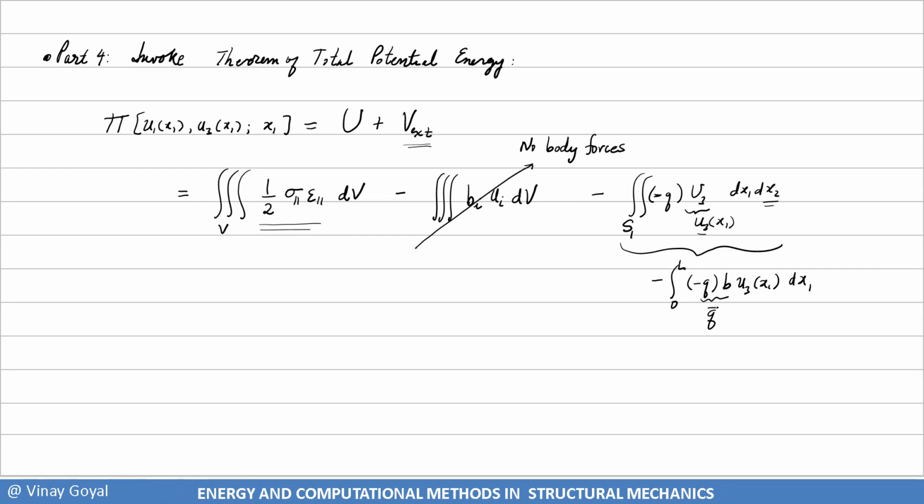So now I have Q in units of force per inch squared, or length squared, and now there's units of force per unit length. So things have simplified further. Sigma 11, I want everything to be written in terms of U1 and U3. I have achieved that so far, except for here. So I have to start doing that. Sigma 11 is E epsilon 11. That'll get me closer to my goal.